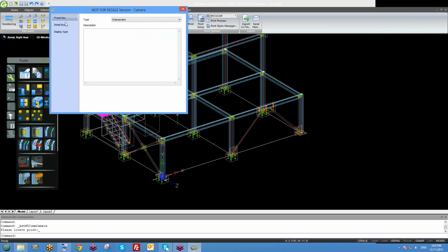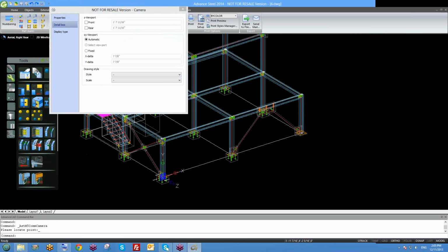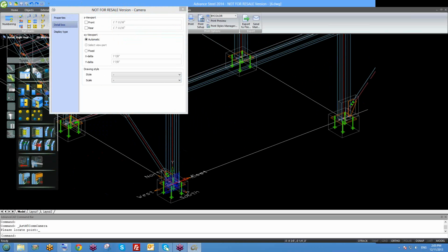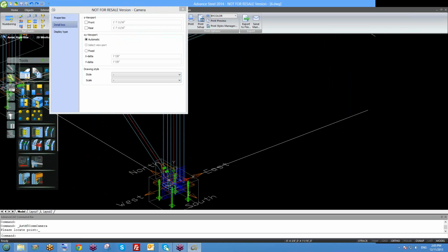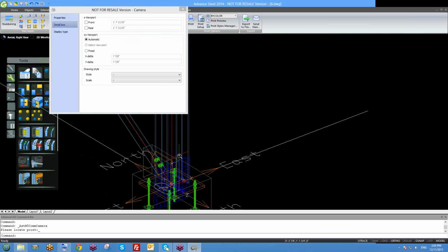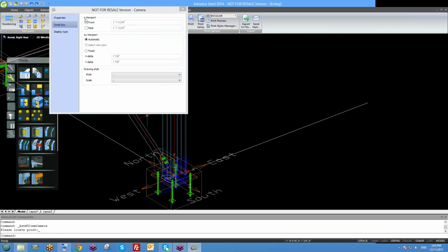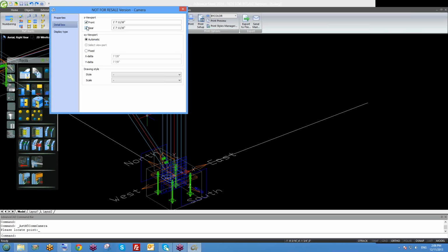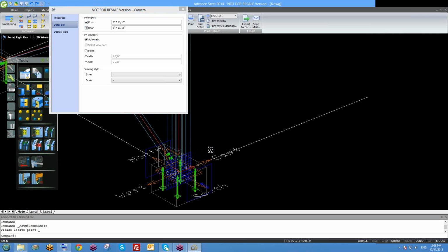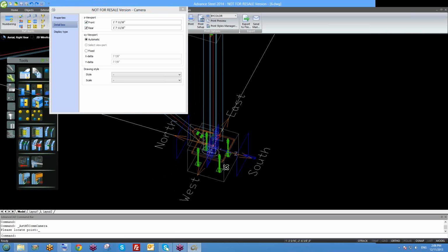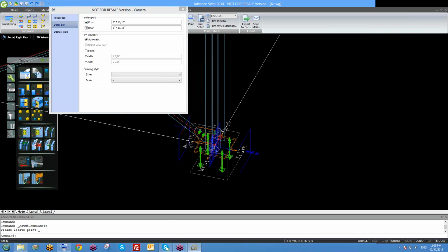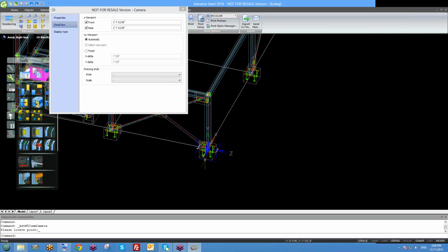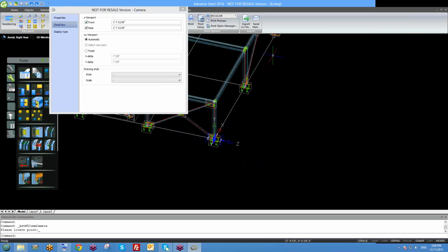All right. Let's go to detail box then. When we use cameras, we need to specify the depth of the camera. So under Z viewport, make sure you have these front and rear checked. And then do an orbit on your model to see what you're going to get. So this is going to be the part that will be detailed all through this bay.